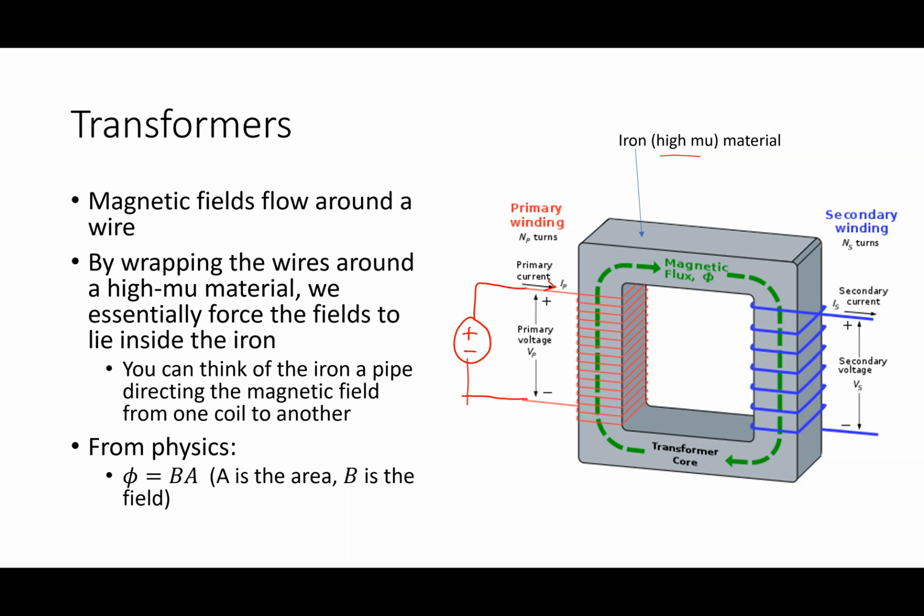There's ways to make transformers smaller. That would mean changing the frequency of the power system to a much higher value. Mobile power systems like in vehicles or ships will do that. Aircraft have a 400 hertz power system, which makes things smaller. But that's kind of outside of our scope here.